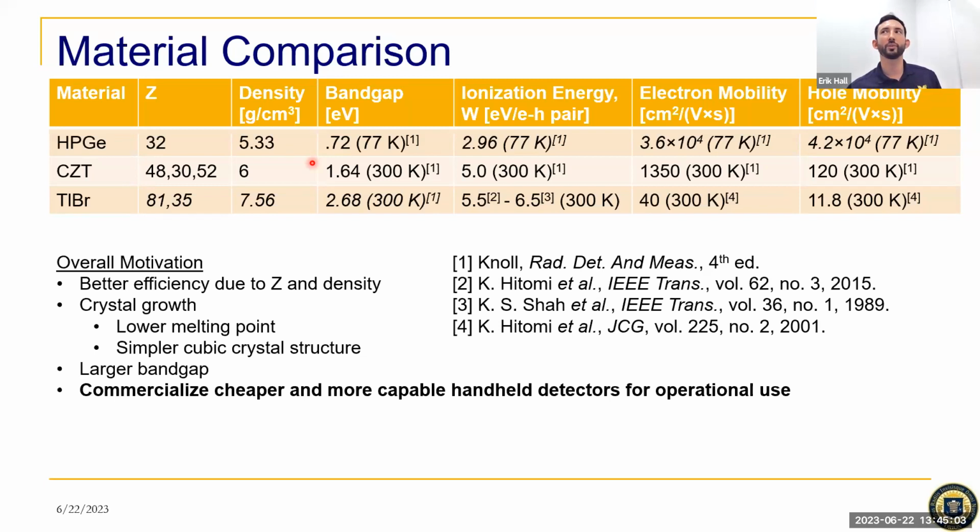Those crystals would provide really good spectroscopic resolution, easily 1% at 662 keV. But they suffered from polarization, where you would see the photopeak on the first day when you operated at room temperature, and then a couple of days or even a few hours later, the photopeak is gone. The signals just have a very inconsistent amplitude.